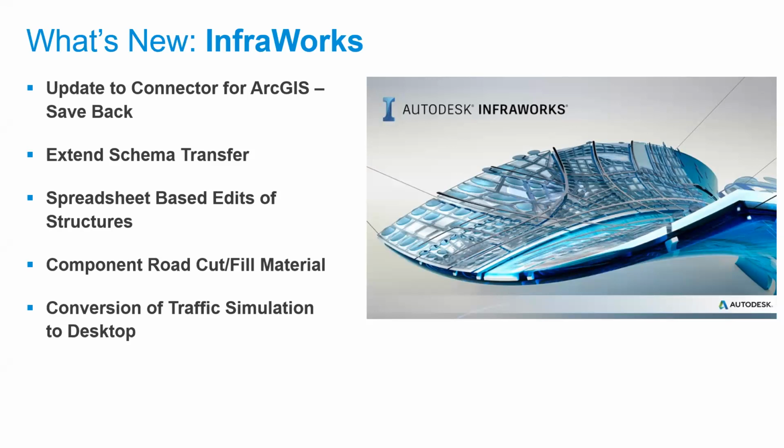And also, more importantly, is the conversion of traffic simulation to desktop. For those who have used the traffic simulation within Infraworks, you realize that in the previous releases, you could only perform traffic simulation in the cloud. You first had to define your traffic study area, define your traffic demand, then it would go into the cloud, perform the simulation, then you could download it and start playing it within the Infraworks model.